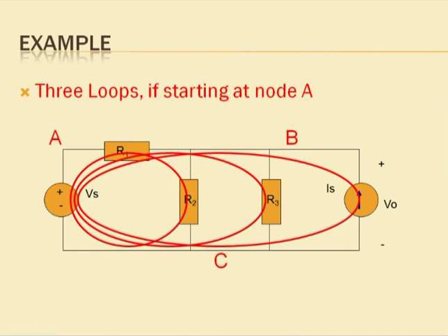According to my standard convention, I am considering this voltage drop positive. But now say I am moving from branch C to node C to node A. In between node C and A, I have one voltage source. As you can observe, C is connected with the negative of the voltage source, A is connected with the positive of the voltage source.